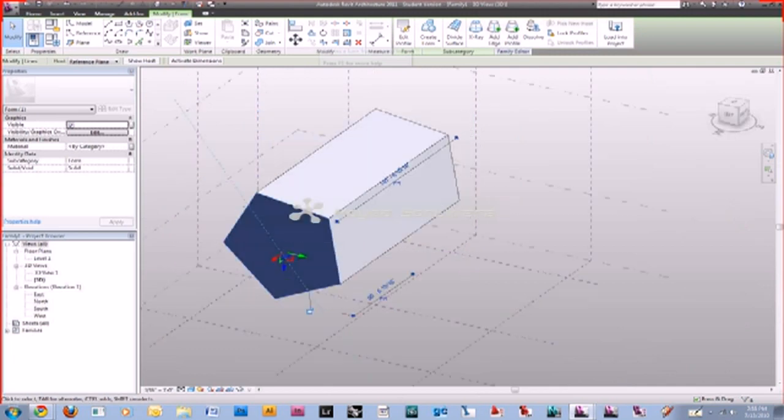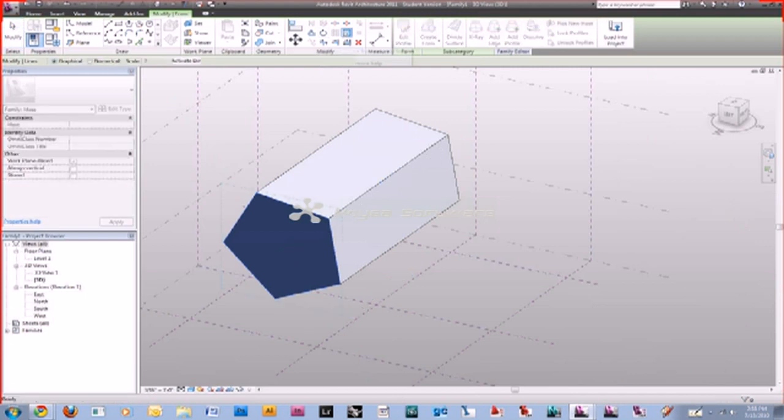So if you select this, you still have some of your modifying commands like scale and rotate. So let's say we scale this first. I hit scale, then I go here and say I want this point to this point to be 65 feet. Click those two points and I can stretch it out some. Let's say I want it to be 100 feet. So I'll type in 100.